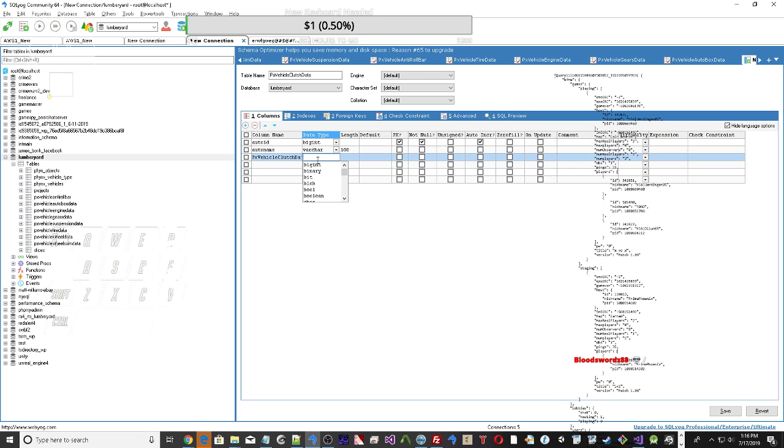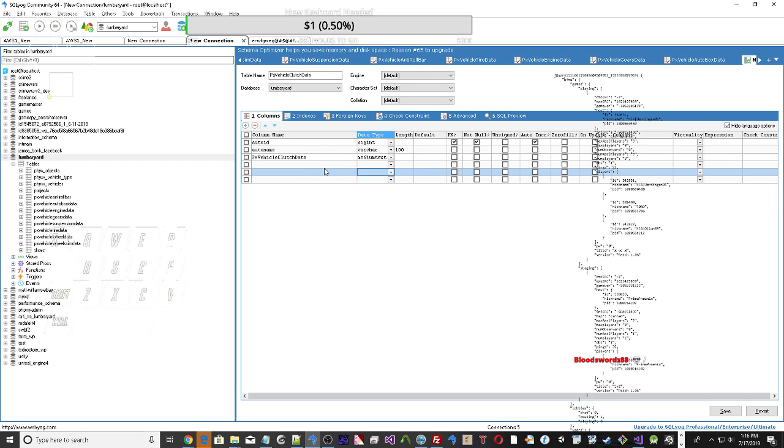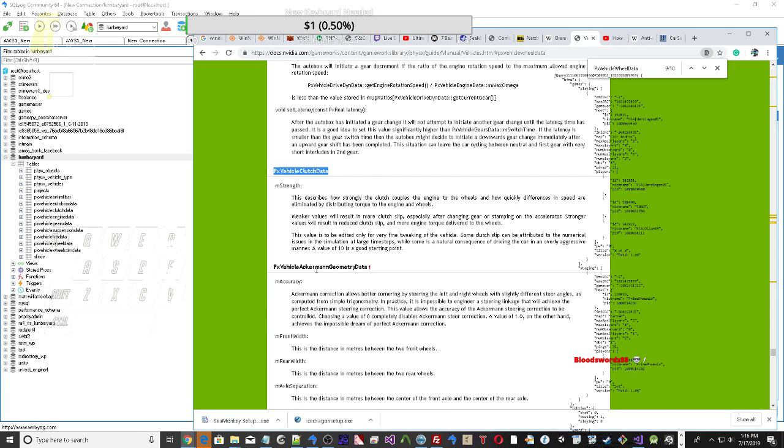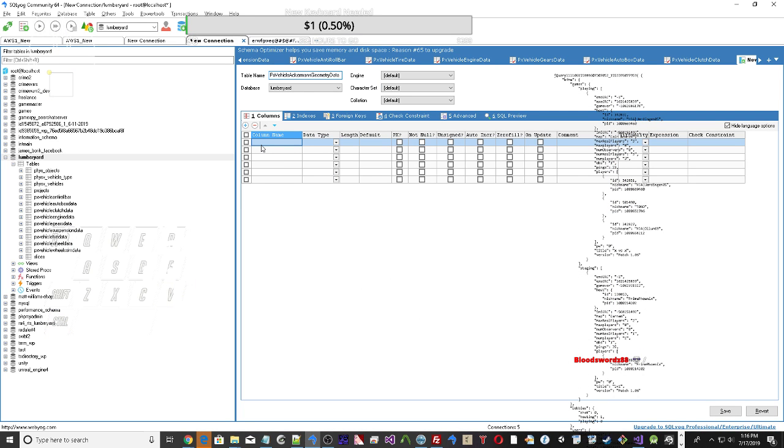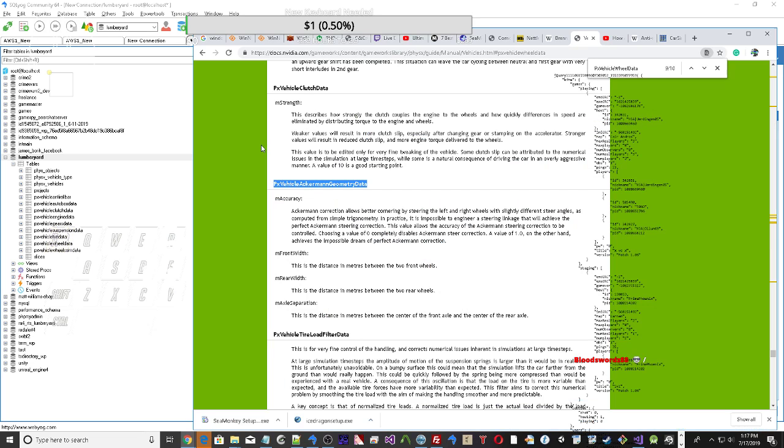The effective rotational speed of the other side of the clutch can be computed directly from the gearing ratio and the rotational speed of the wheels that are coupled to the clutch through the differential. This model naturally allows engine torques to propagate to the wheels and wheel torques to propagate back to the engine, just as in a standard car. The data describing each component of the Physics vehicle can be found in the section Tuning Guide.